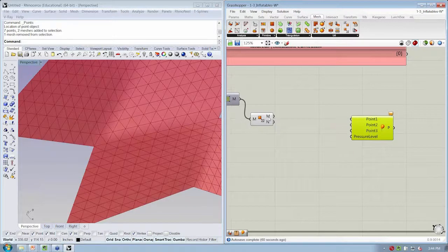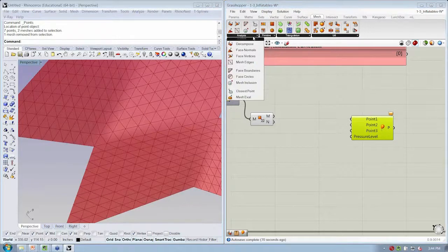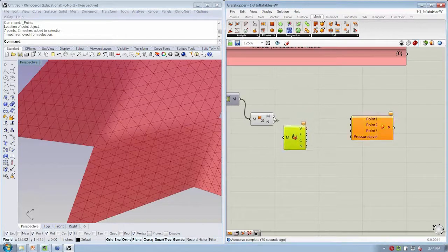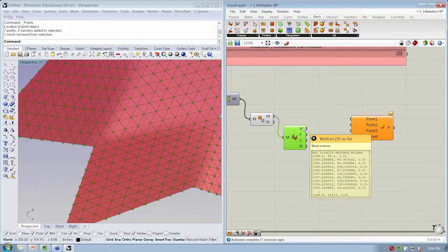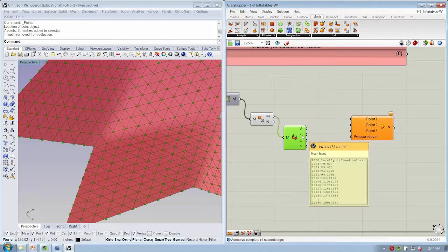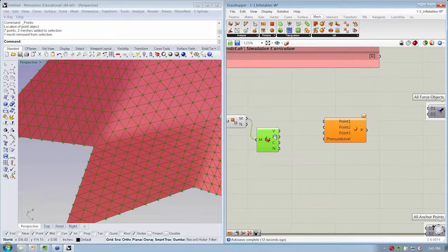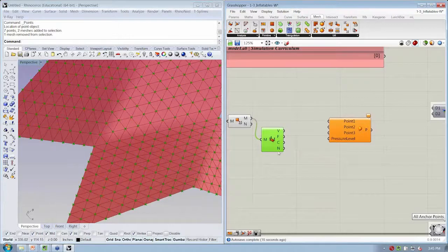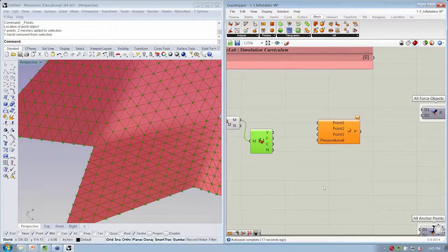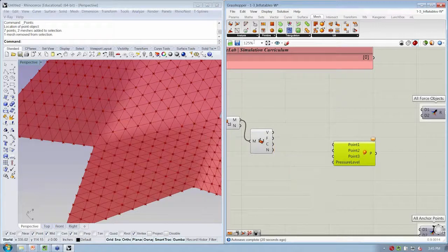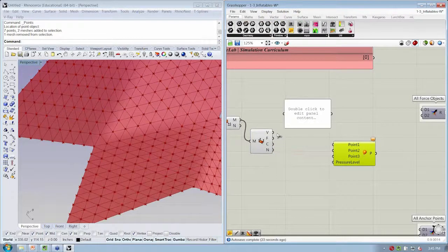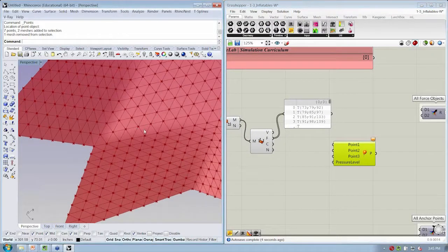We're going to take our mesh and decompose it, just like we did before. So under Mesh Analysis, Decompose, take our mesh and decompose it into vertices, which is one long list, the mesh faces, and these are our commands to say which 3 points should be connected, the colors and the normals. And we don't need to work with the last 2 outputs, but we do need to work with the vertices and the faces. Okay, so how do we go from the face command to individual values that describe which vertex in the collection we're going to use?